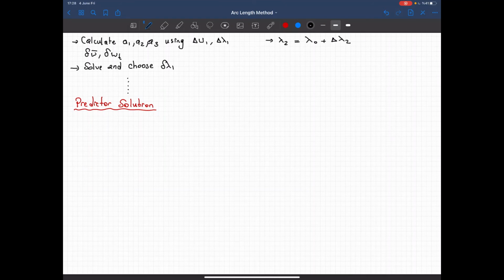So one approach is, we can say that delta P is equal to KT inverse delta QE. Okay, so that's the typical solution that we'll do in the Newton incremental iterative solution with the Newton-Raphson method. So multiplying both sides with delta lambda predictor will give me this.